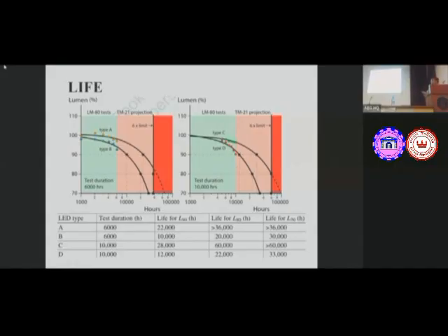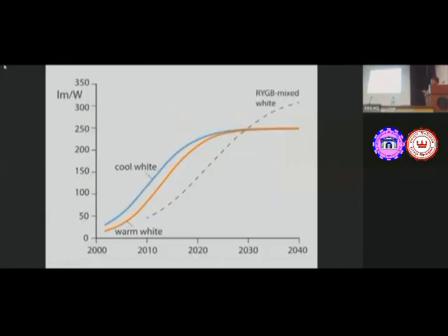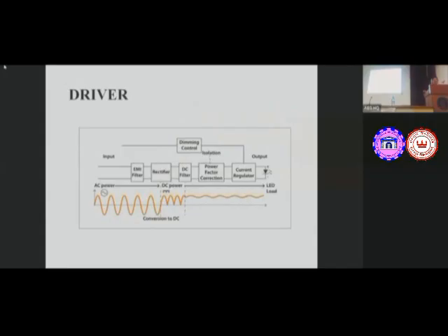DC supply. And not only that one, there is another function that it generates a high frequency signal. Sometimes what happens, when I put a 230 volt power supply over here, that high frequency signal also goes back to the input side. Okay, to the power system it goes. That must be stopped by using an EMI filter over there. It should stop that high frequency signal towards our power supply. Otherwise, it creates a problem. So I was talking about the life of the system.